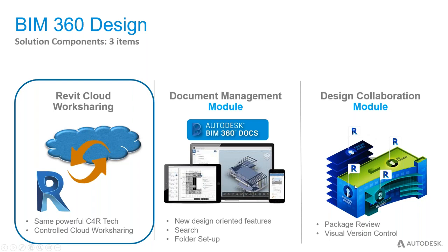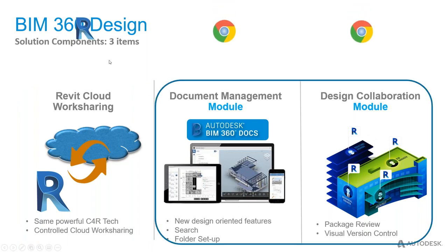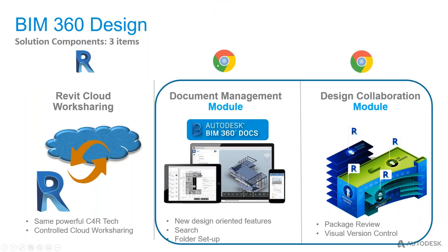This last module here is also a cloud-based module. So you'll see this one sits in Revit. These two are cloud-based. This is the actual BIM 360 Design module in the cloud. I'll give you a screenshot later on. This is the official handover process through what we call packages between the different disciplines. So as I mentioned, yes, the technology is still Revit work sharing, but there's a lot more to it to get to that official handover process between different disciplines.